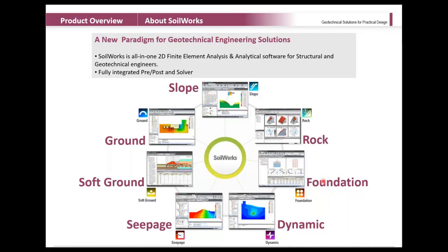This foundation module, as I said, is completely related to structural engineers, where we develop springs, and those springs can be taken back to the civil or any other bridge software. So what we do here is PY nonlinear analysis, where lateral load versus lateral displacement curves are found, and those curves act as spring constants, like multilinear springs in your structural software, which will help you in analyzing and designing your infrastructure project.